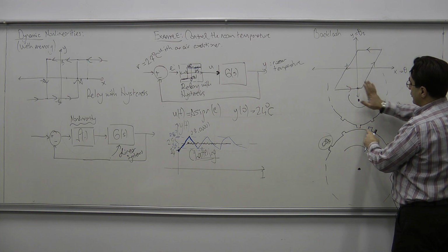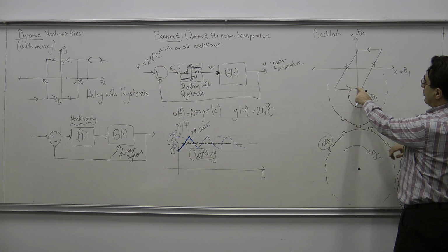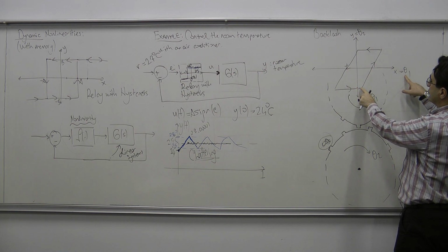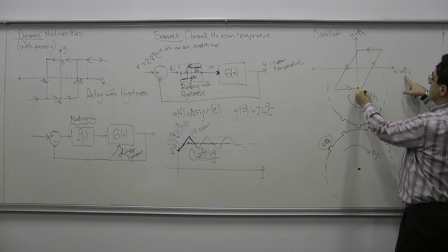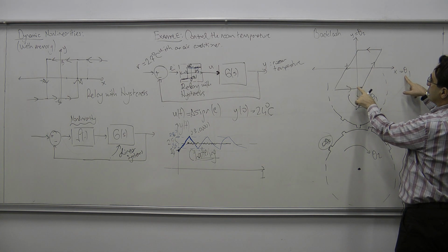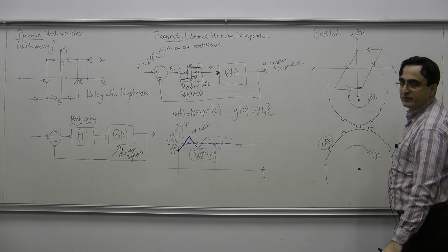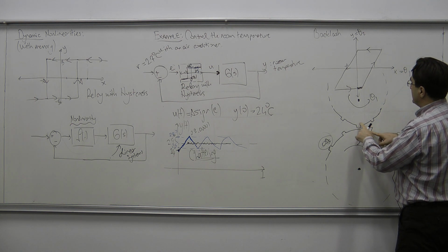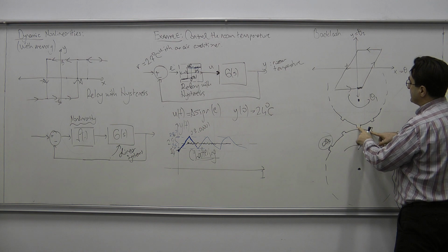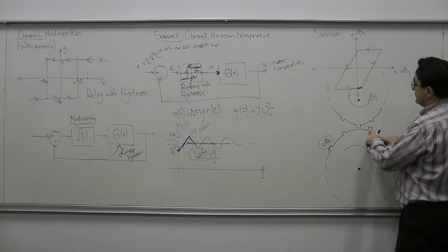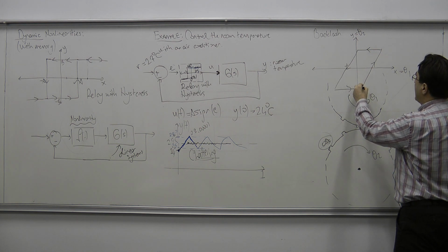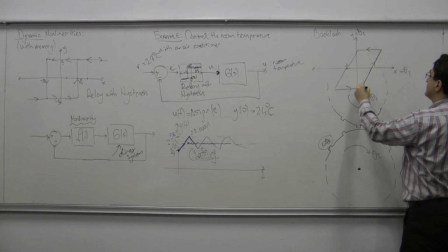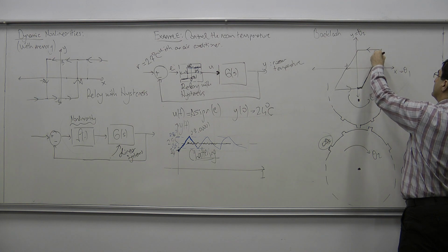So when I turn θ1, for some θ1 values, θ2 is going to remain constant where it is. And only after this cog touches this cog, we are going to have a motion in θ2. Let me say that this motion is like this.